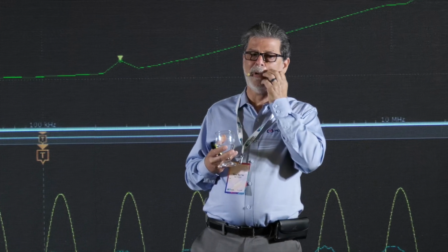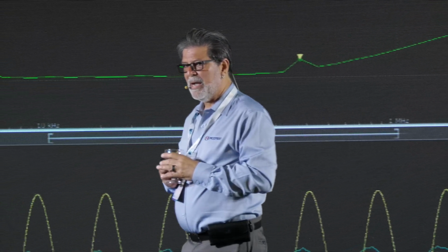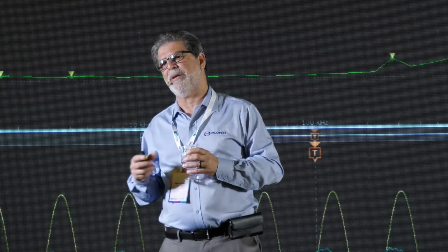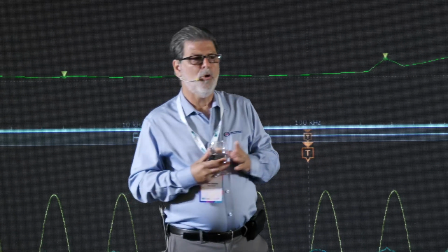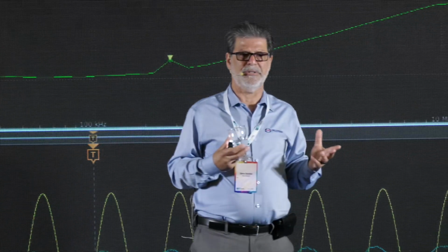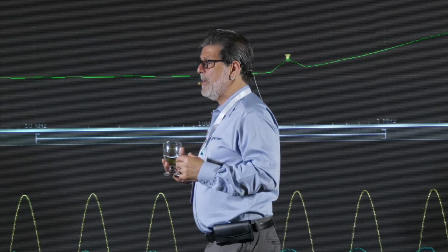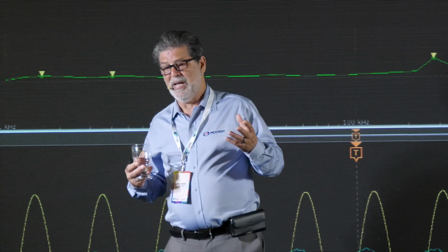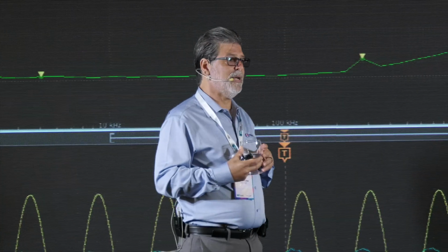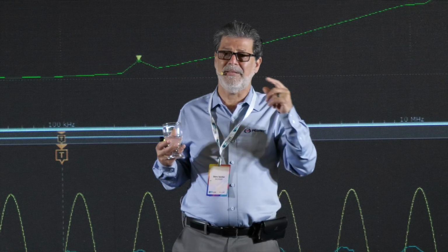Tomorrow, if you come to my paper, I'm going to talk about the fact that good regulation is a terrible thing. In fact, I'm going to show you that the trick to fixing our clock problems is to degrade the regulation of our power supplies. Remember that what's really important to the chip is noise, right? Our load chips are sensitive to noise. They may be sensitive to noise in certain frequency ranges, to certain amplitudes, or to certain current perturbations. As a power integrity engineer, my job is to assess all of those